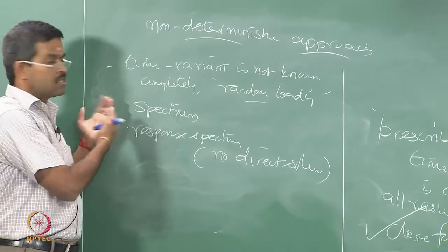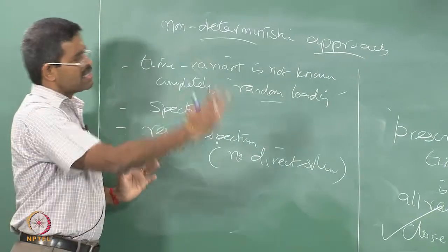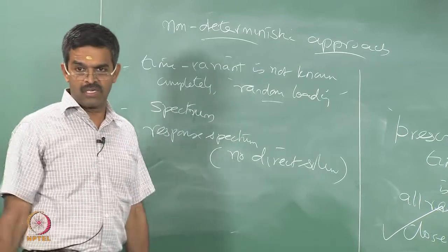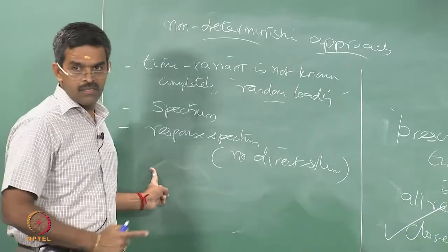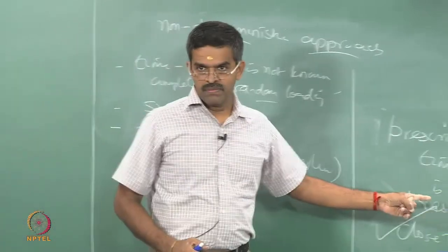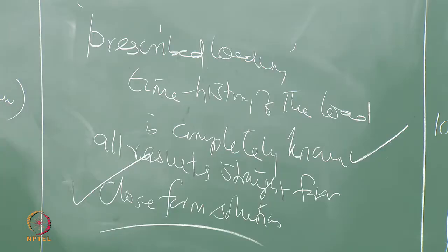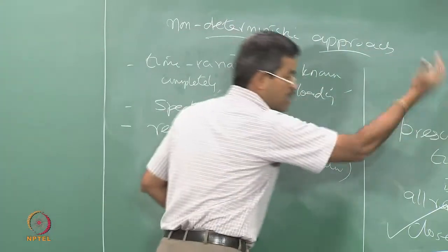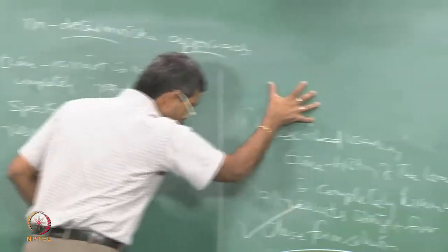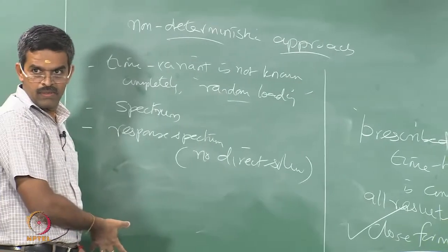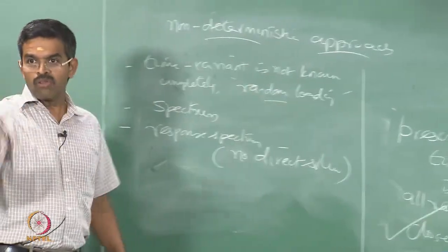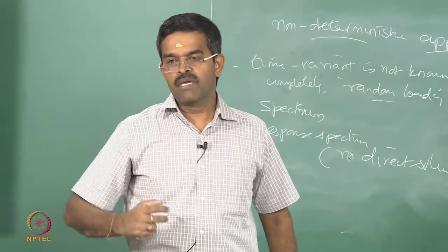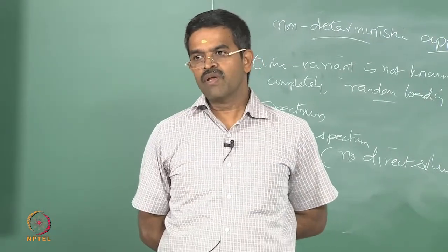So, they are non-deterministic. Now, you see there is a combination of different types of forces acting on the structure. What analysis should I do? Should I do a spectral analysis? Should I do time history? Either way you can convert them into time history and do an analysis, or you can convert this into spectrum and do an analysis. This is what we call time history analysis, and this is what we call frequency domain analysis. Both are available for dynamic analysis of offshore structures. Both domains are all right.